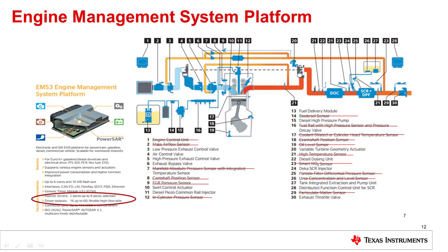In taking a closer look at a typical engine management system platform, there are a myriad of sensors and outputs. Outputs are anything that can be controlled by a driver, and inputs are any sensor that can measure the parameter of interest and convert it into an electric signal. There are as many as 60 high-side, low-side driver outputs and 8 injector drivers to control in an EMS.